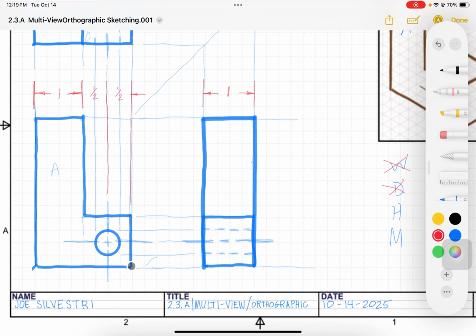So I always start in the lower right-hand corner where I'm circling. I'm going to do my 1-2-1, so I'm going to leave a 1 block gap like this. Then my dimension line will go here 2 blocks away, and then I'll have 1 block of the extension line extending past.